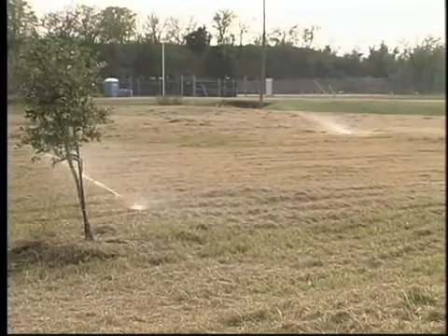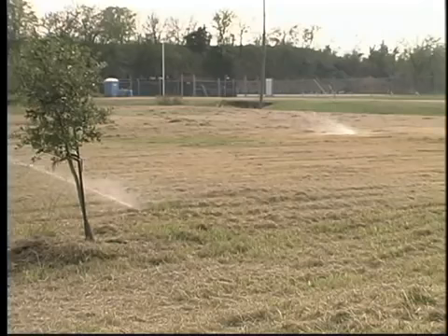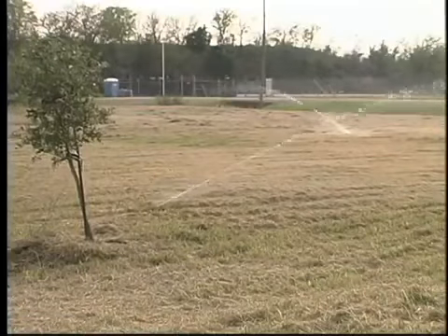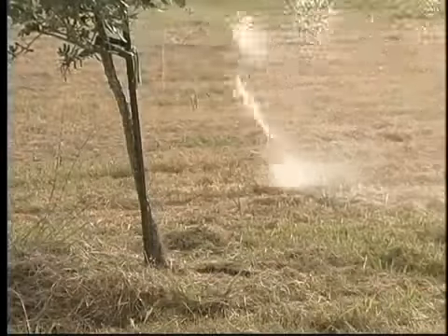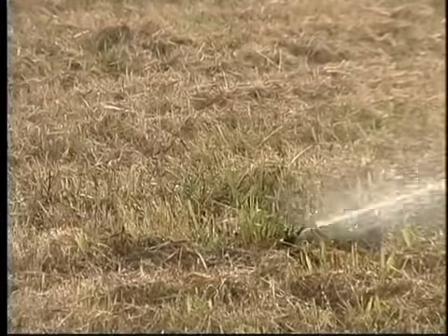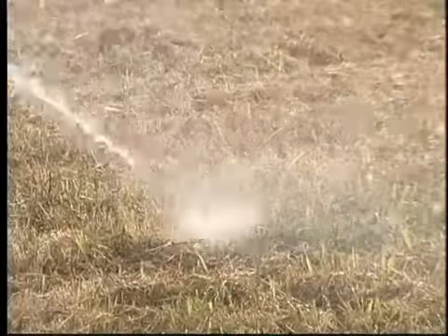Therefore, the system requires the highest quality effluent from the pre-treatment system. Wastewater must also be disinfected. The surface area must have vegetation and be landscaped to avoid runoff. Also, low trajectory sprinklers are used to minimize drift from the spray area.